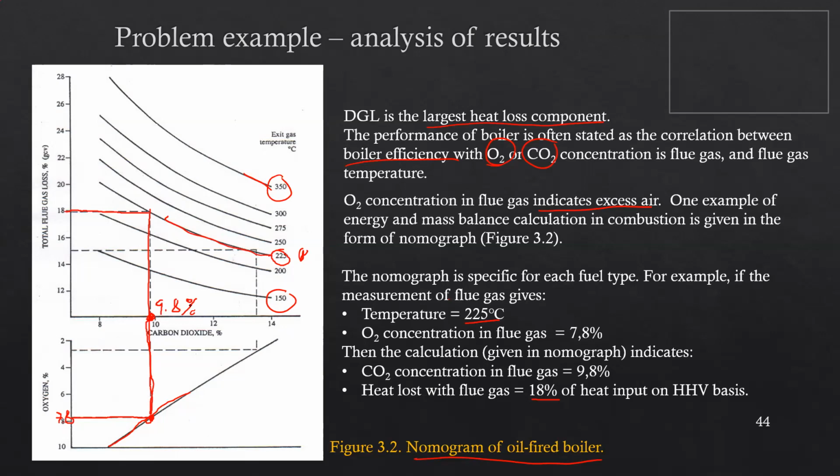It's a good question. So for the heat losses, why is it actually on an HHV basis? As far as I know, this is the rule of thumb for the heat losses based on this nomograph. The percentage is divided on the y-axis here. This is already stated as a GCV, the gross calorific value, which is similar to the HHV basis.